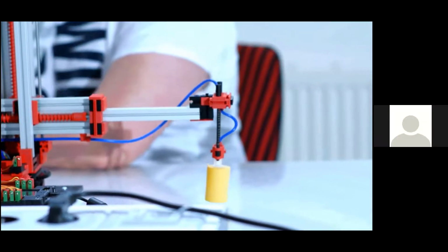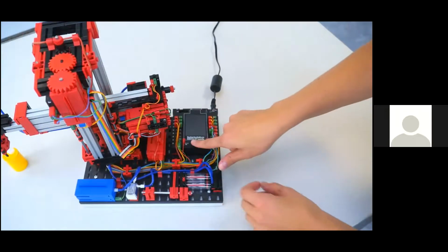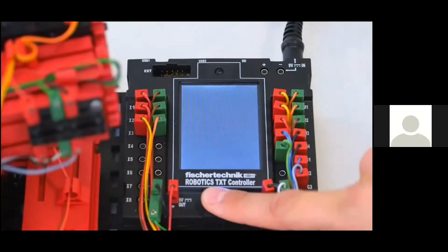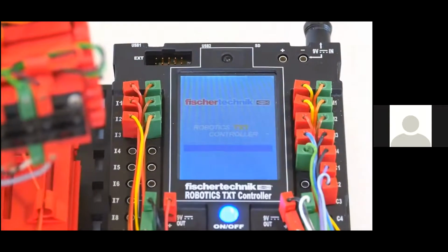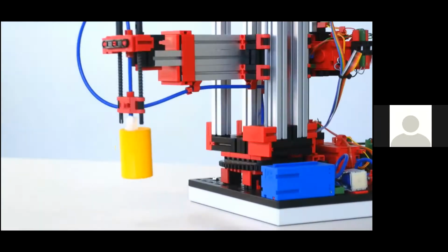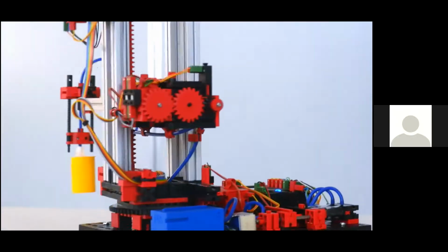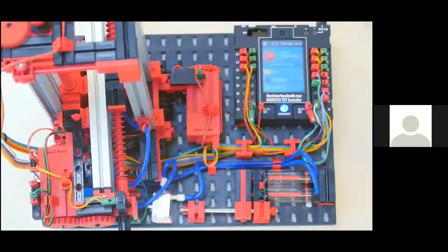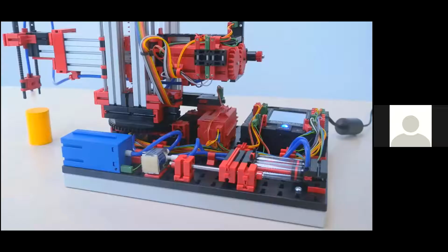The 24-volt versions of this model, as well as all of the first five 24-volt models we're going to be looking at today, each have a relay board for motor polarity reversal and both a multi-pin connector, 34 pins with a grid of 2.54 millimeters, as well as additional PCB terminals with push-in connections for all inputs and outputs. Again, the 24-volt version of this model, as with all 24-volt versions, will require you to provide the PLC and